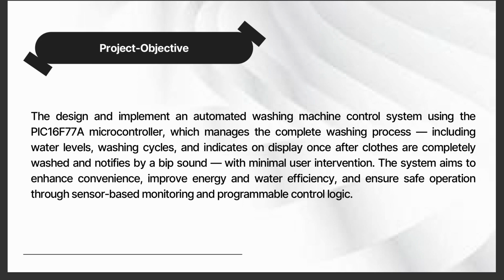We chose the PIC16F877A microcontroller due to its multiple I/O pins, timers, analog to digital converters, EEPROM storage, all essentials for controlling multiple hardware components in real time.